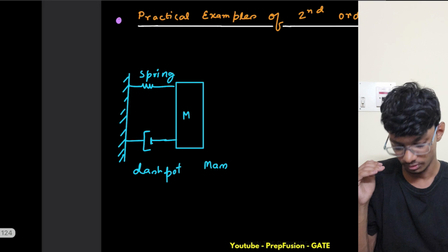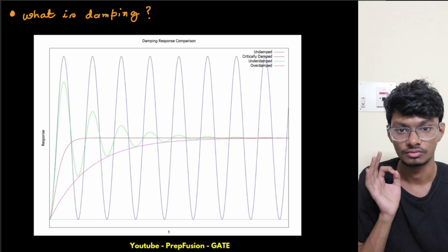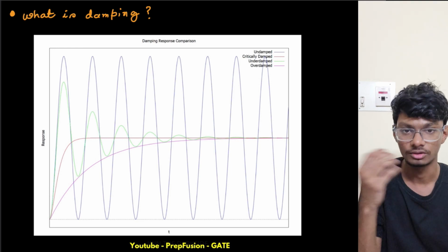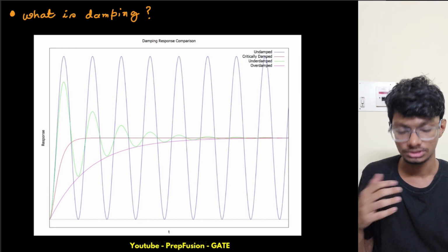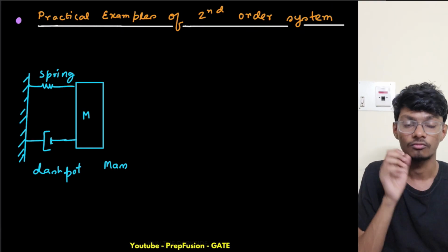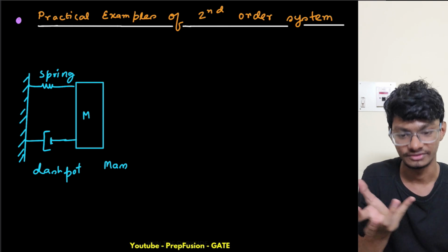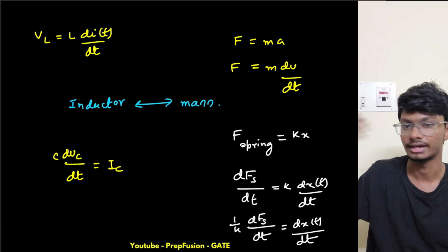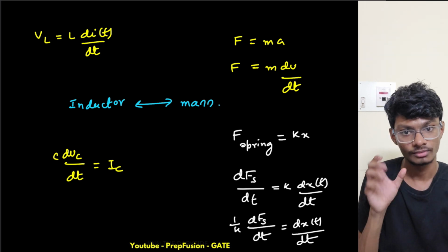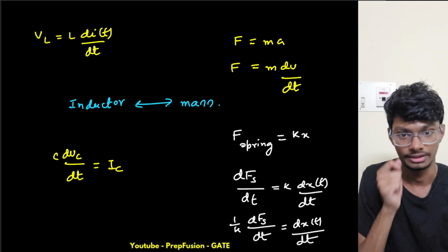And the main thing is that this undamped, sinusoidal behavior, we will actually not achieve in real systems. Why? First case is obviously we'll derive, and there also we'll understand why. Because for this to occur, the friction has to be 0. Now what provides friction in a mechanical system? In a mechanical system, obviously friction provides friction, like on land everything is friction. Air also has friction, air drag, everything. So energy is being lost everywhere. That's why in real mechanical systems I won't be able to make my friction 0, it is impossible.